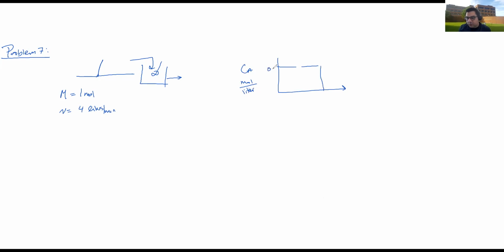And our maximum concentration is 0.05. And this is time 5 minutes. So I want to compare these two. Basically, I want to do mass balance. And the approach to do this is, the only information I have which is close to a mass balance from the chart here is the area under the curve.